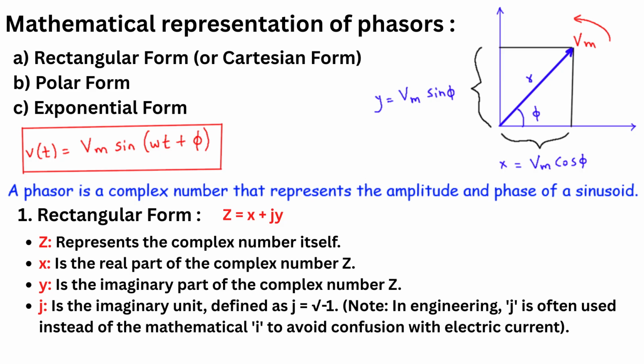Next, we have Vm. This is the amplitude. The M stands for maximum. So, Vm is the peak value, the highest point the voltage wave reaches in its cycle. If you imagine a wave on the ocean, the amplitude is the height of the wave from the calm sea level to its crest. When we say the power from a wall outlet in North America is 120 volts, that's actually a related value called the RMS voltage. The peak voltage, Vm, is actually higher, it's about 170 volts. So Vm tells us the strength or intensity of the wave.